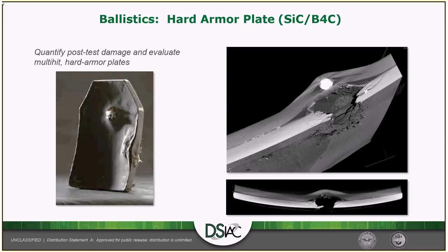And then lastly, you can get the depth of penetration real easy. You can see from the top down view, you can see that bulge in the backing material. You can do all digital measurements in the software and actually pull that depth of penetration out and get a more accurate reading than you would on a clay surface or what the traditional ways are.